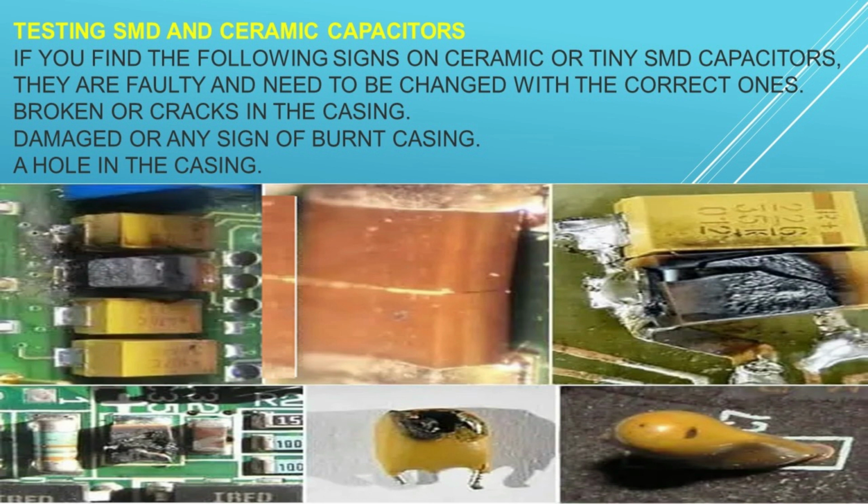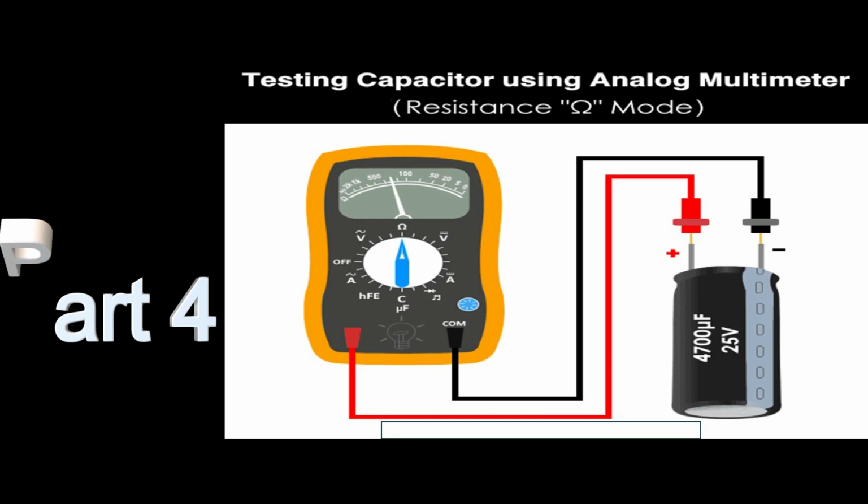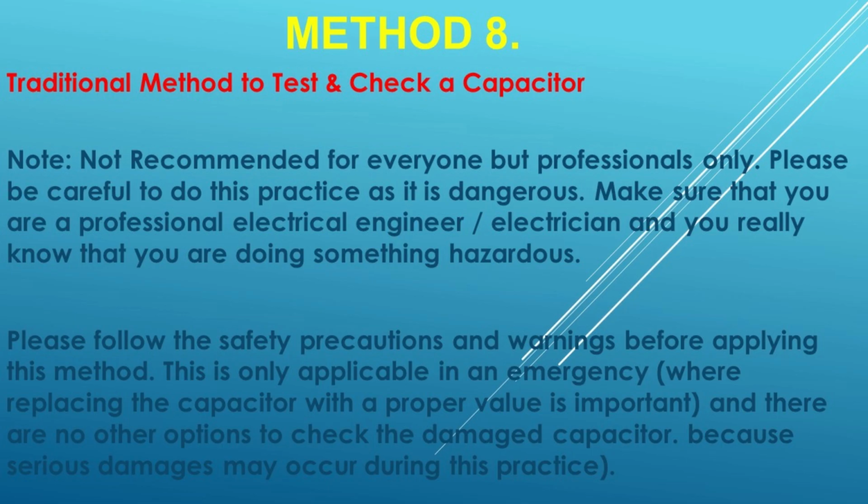Bulging top vent of capacitor. The top vent of the electrolytic capacitor in shape of K, T, or X are the weak points made to release the pressure during the failure of a capacitor to avoid serious damage to the surrounding and any other components connected near to it. If you find a bulging top of the capacitor, it is the electrolytic discharge, black, white, orange color, which depends on the electrolytic material, i.e. the capacitor releases a gas pressure during failure and breaks the top vent of the capacitor.